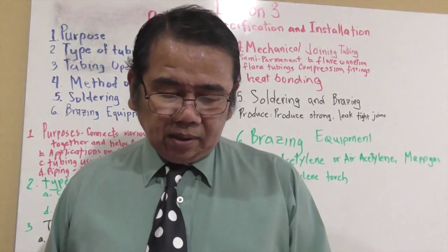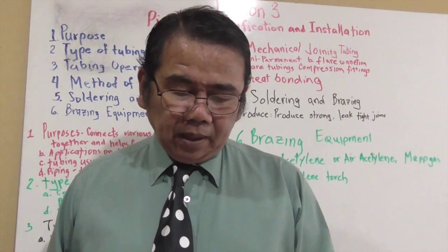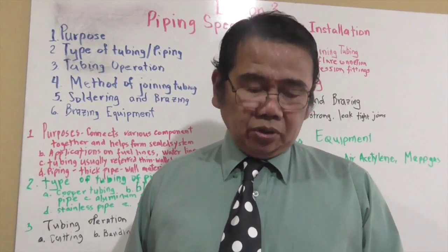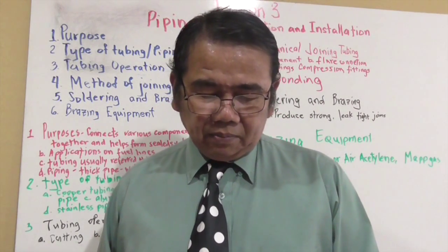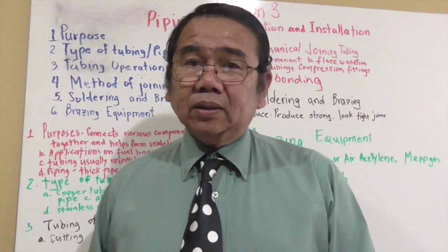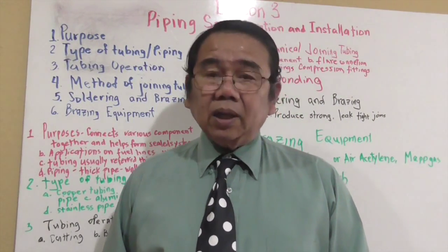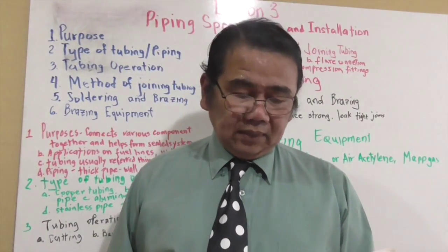Apply silver solder against the fitting and the tube. If heated correctly, silver solder will flow freely into the joint. Cleaning after brazing. Okay, when you get done brazing, do not quench. Do not dip it into the water. Allow to air cool until the brazing alloy is set.